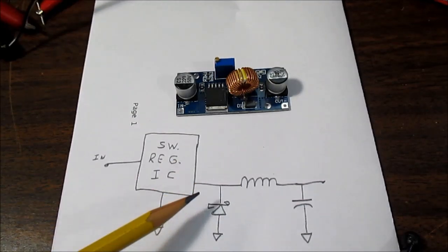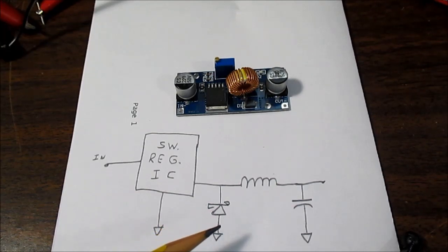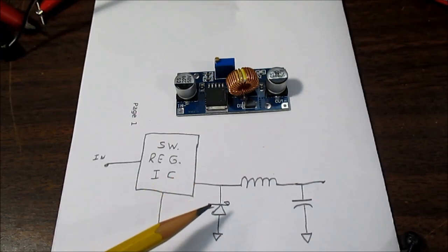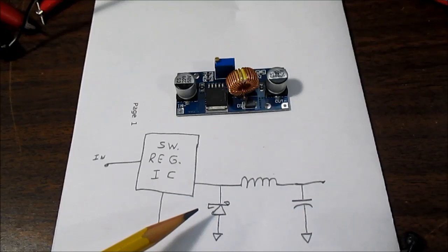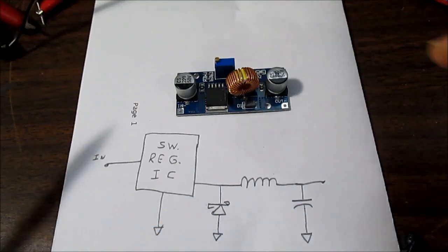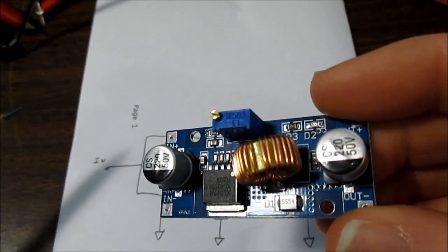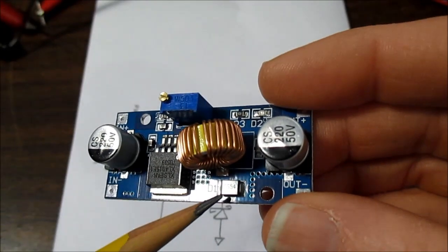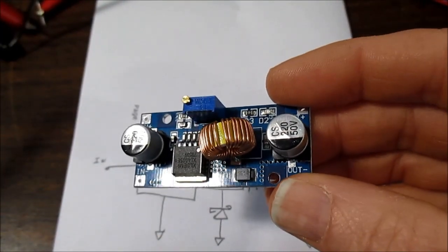The designer of the circuit has to weigh all the properties, the forward voltage drop, the switching speed, and the extra capacitance to see if it's the best type of diode to use in their circuit. In this example, this is a little switch mode regulator. It has an SS54 flyback diode right here, and it turns out to be a Schottky diode.